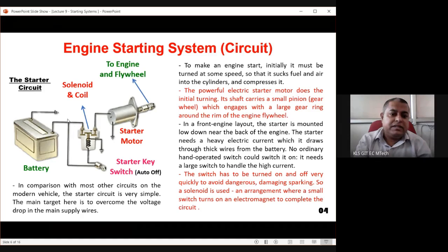Okay, so in the first stage, just turn the key to the right, current flows through the coil, and this connection is established. As soon as this connection is established, by the time the start key is off, meaning no current is flowing to the bottom part, all the current flows to the top part through the heavy wire, and the starter motor is getting electricity. As soon as the starter motor gets electricity, with a very strong thrust, because it is a DC series motor, it actually engages.